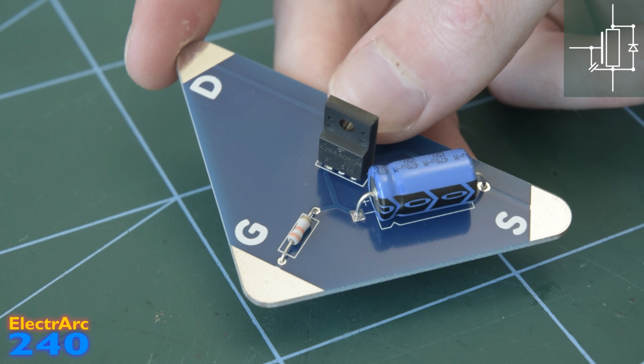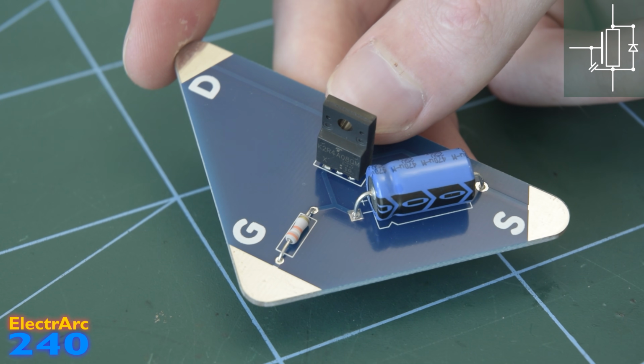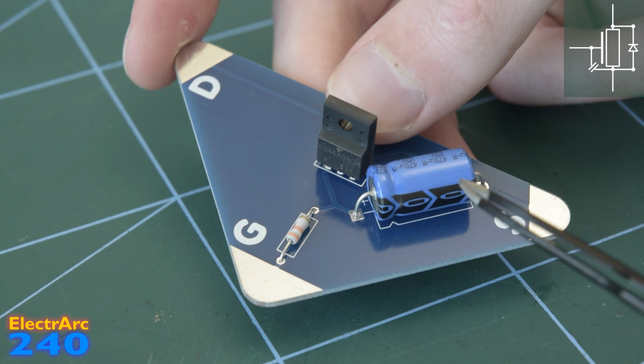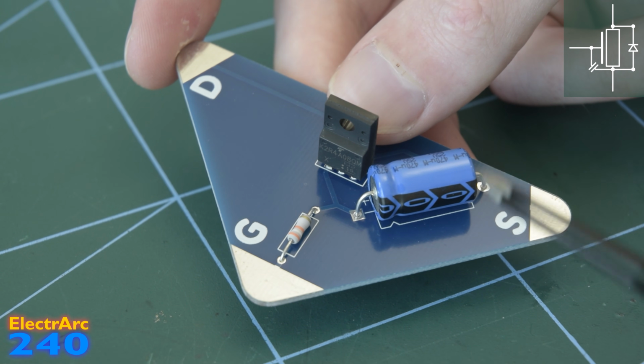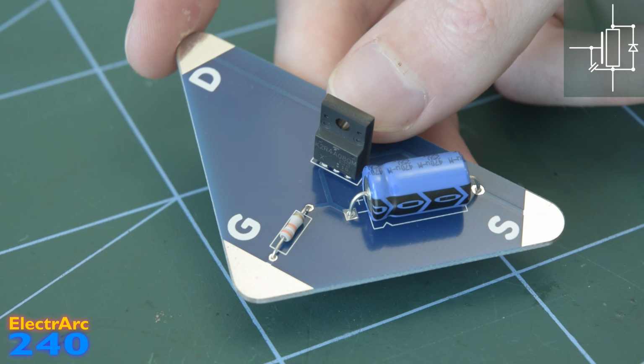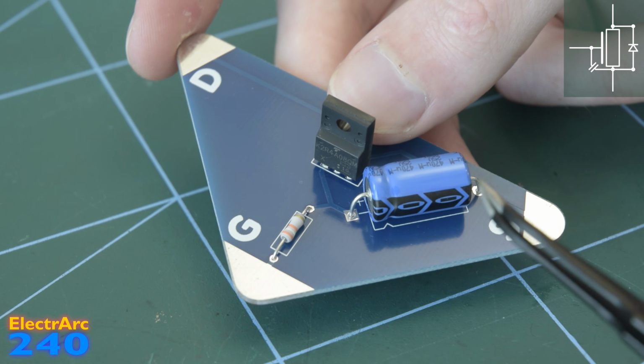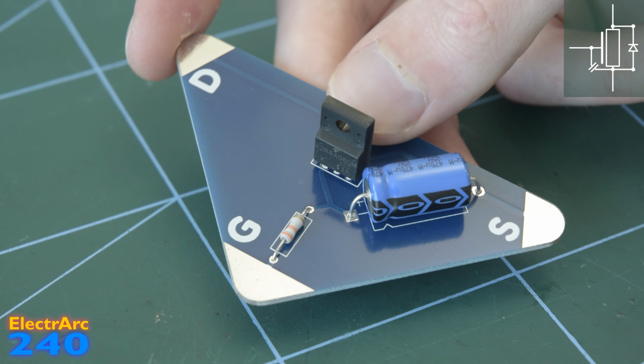capacitor that has to be charged to turn the MOSFET on and discharged to turn the MOSFET off. For example, if you just disconnect the gate circuit while the MOSFET's on, it will probably just stay on because this gate source capacitance holds the voltage that's keeping the channel open. Well, that's not a problem. You can charge and discharge a capacitor really quickly if you've got enough current.